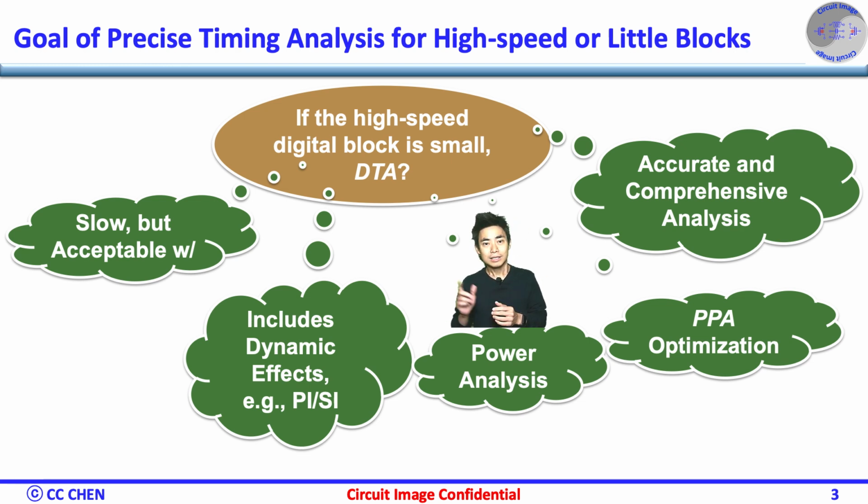To be clear, the verification in the DTA must incorporate SPICE simulation precisely to capture the dynamic effects, such as the high-to-low or low-to-high transition, clock data skew, and jitter accounting for the arrival time uncertainty, power consumption, or supply-induced noise jitter, and process variations over different process nodes. Finally, the goal of the DTA can also help evaluate different process nodes with PVT conditions, different digital blocks, like static flip-flops or high-speed customized flops.